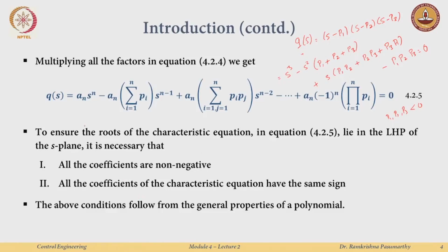So, the first observation, just by an expansion like this and keeping in mind that stability would mean the poles are on the left half plane, would lead us to say the necessary condition is that all the coefficients are non-negative. It could be a 0, but if this is true, all the coefficients would be positive. This follows just from the general conditions of this polynomial. This is a general expansion of degree n.